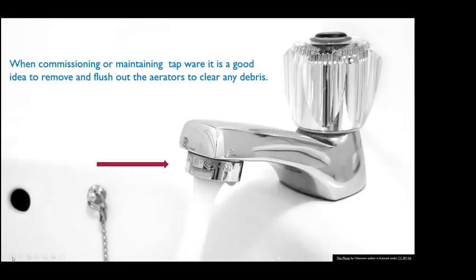We're commissioning things. I think people often mistake commissioning for doing a pre-lining pipework test. So if you're just testing the pipework, that's not commissioning. Commissioning is after you've done all that, basically at the end of the project, everything's finished, you've installed all your fixtures, whole thing's done, then going around doing your final checks to make sure it's all correct.